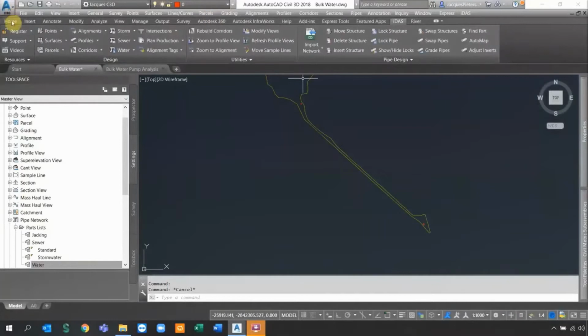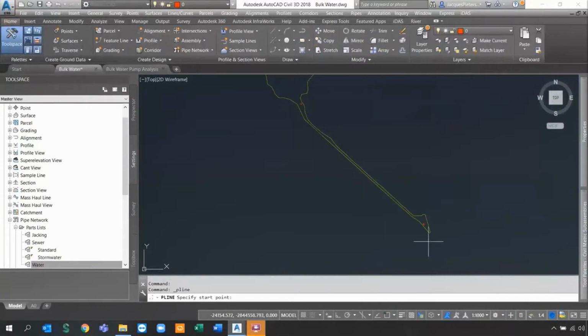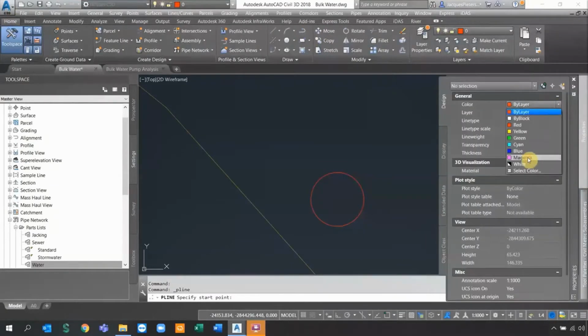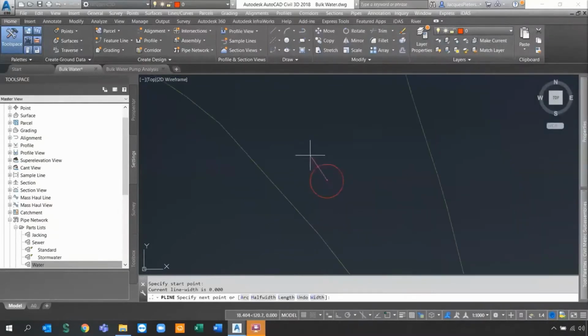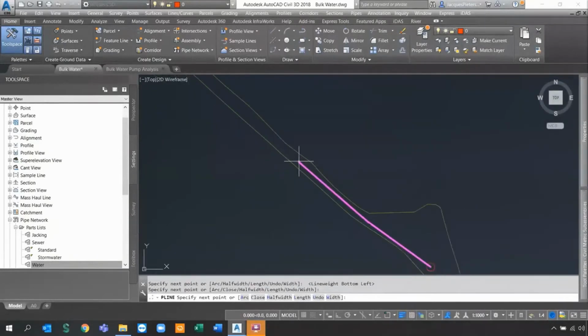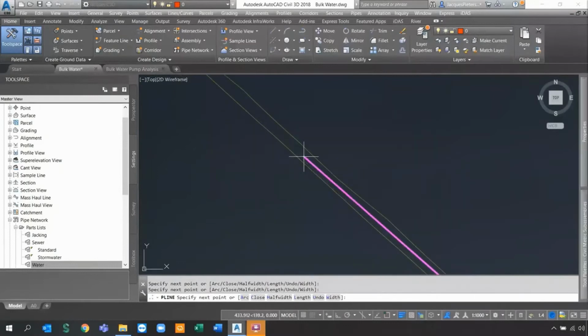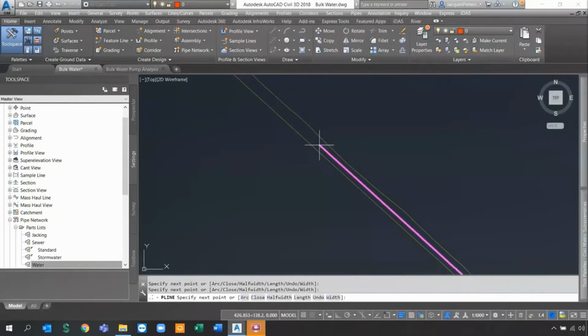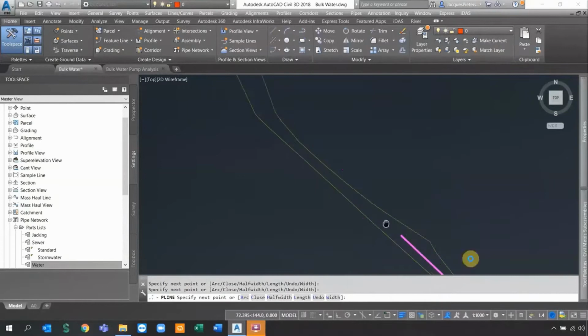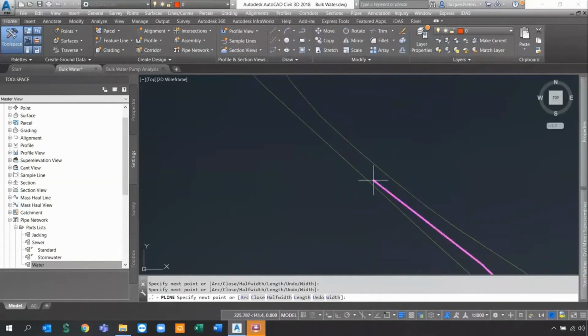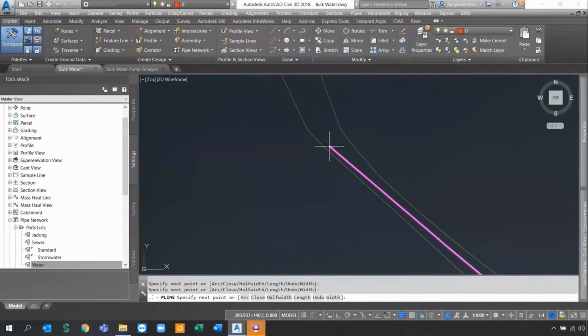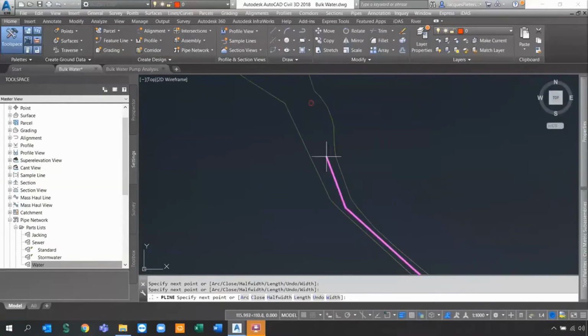Very nice. So the actual step is to go draw this out as a polyline because that's how we can automate our designs to change them into structures and pipes. So I'm just going to set up a nice thick little line. And what you need to do is simply manually go and draw out how you want your pipe network. Now, if somebody provides you with a polyline, you could also bring that in and generate your pipe networks from there.